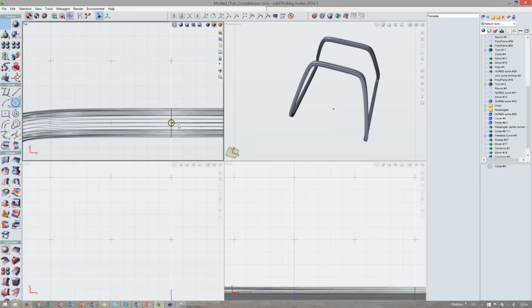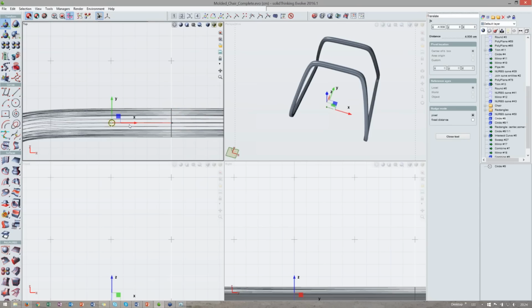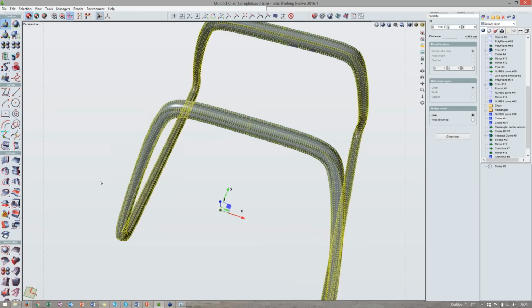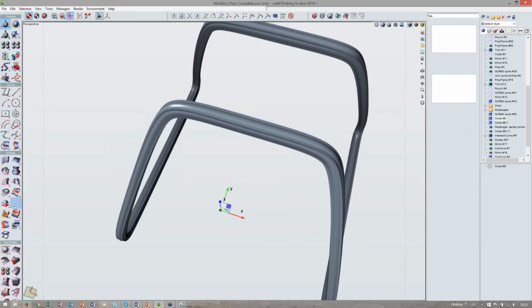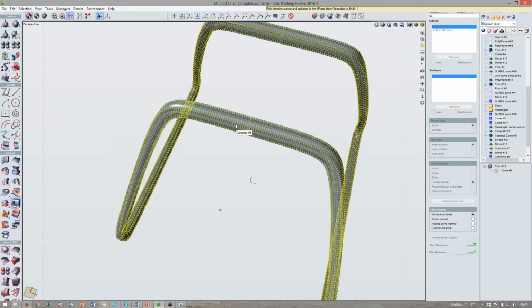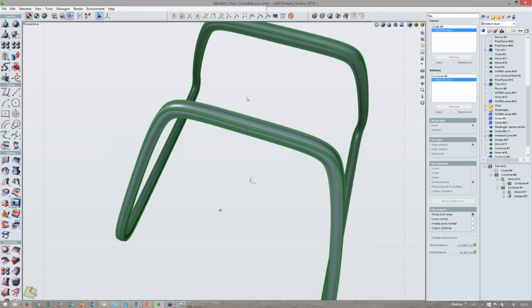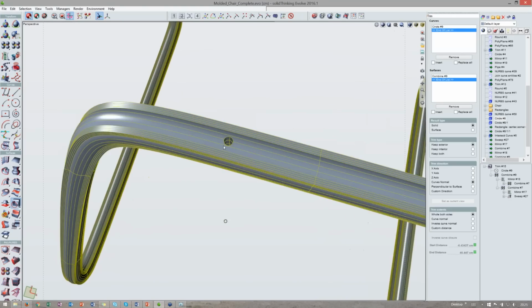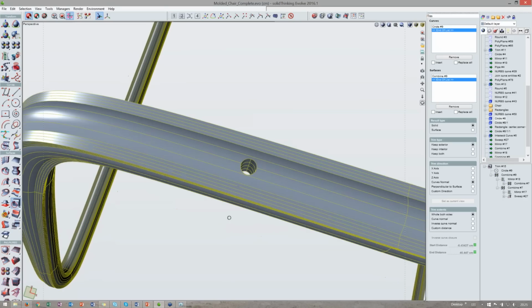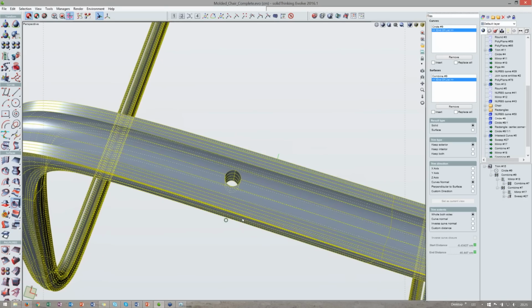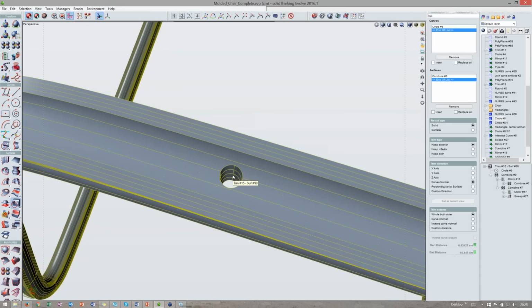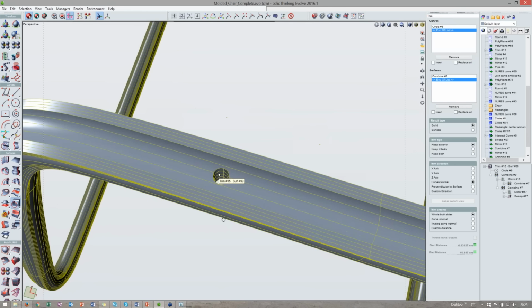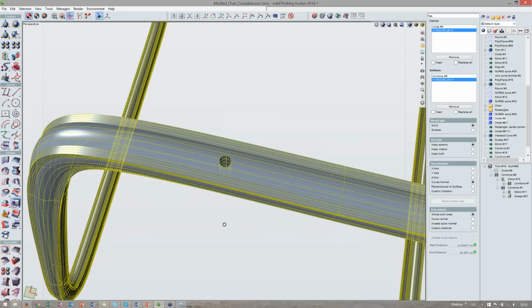This circle, for example, we want to use it to create a hole inside this structure we had, because we want to fix it to the seating, right? So we take our trim tool, we take our small circle, we take our structure, we trim it, and you can see it already. This is a solid because the trim generated my inside surface automatically for this trim. Why this?